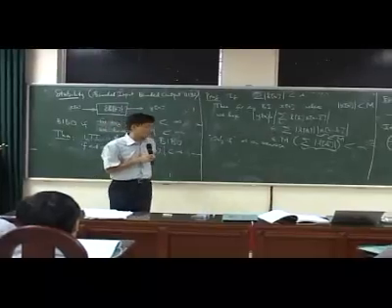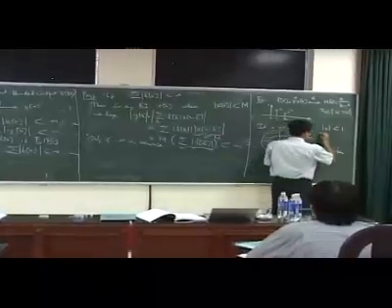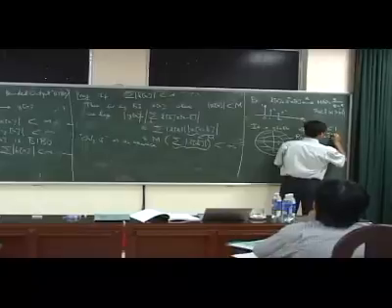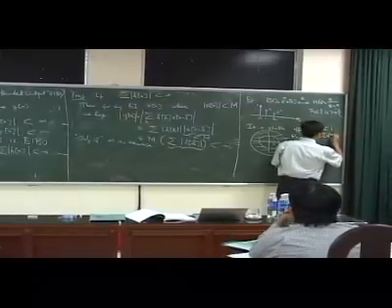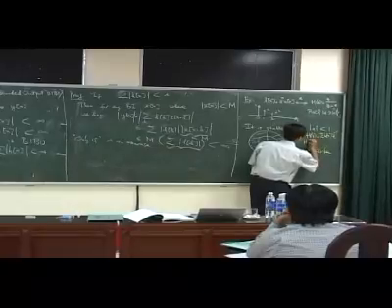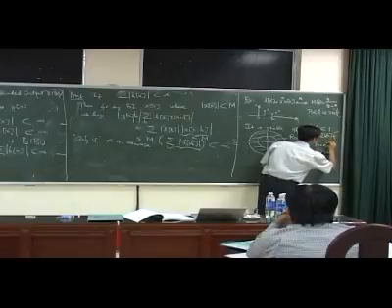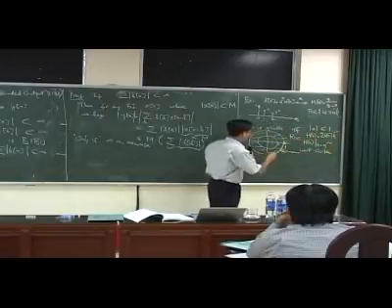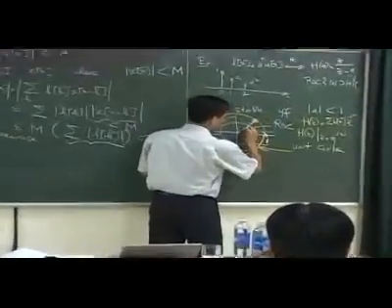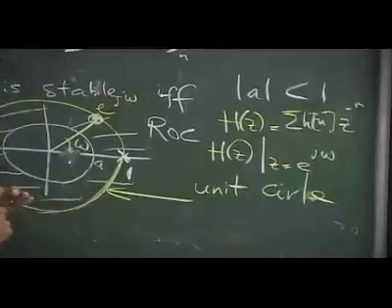We're taking the Fourier transform on that, right? Remember, I have S of Z equal to the summation of H of n Z to the minus n. If I take H of Z, where Z is equal to e^{j omega}, then if this angle is omega, the point is e^{j omega}.